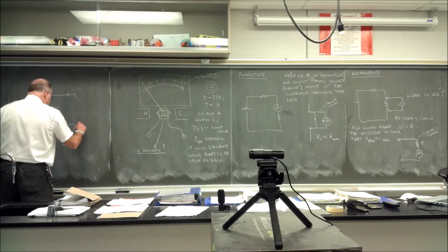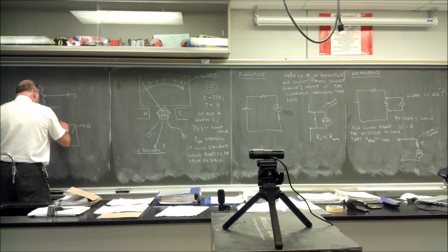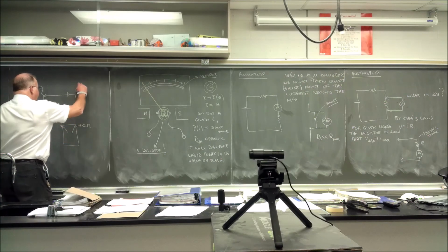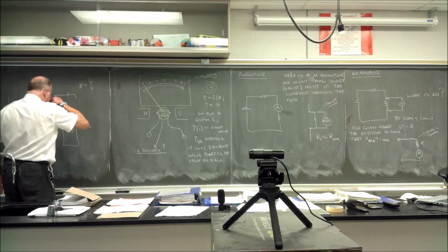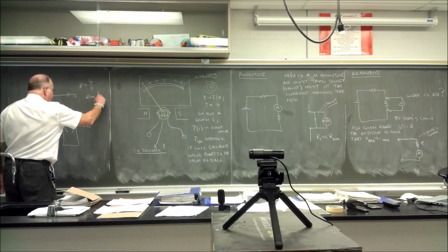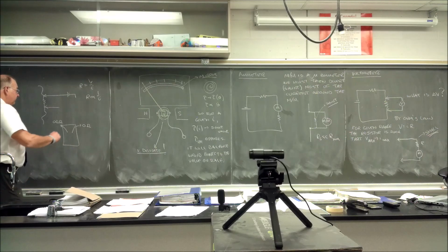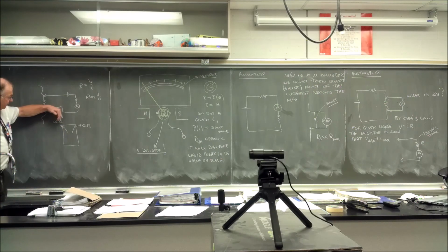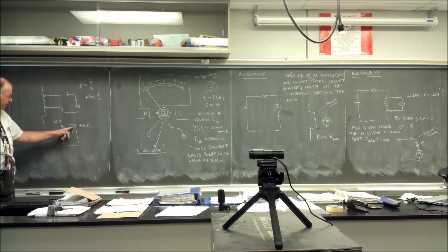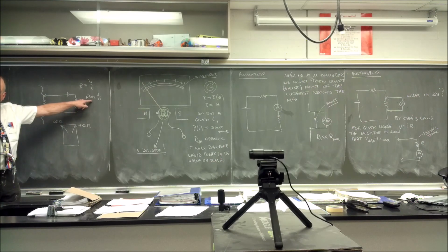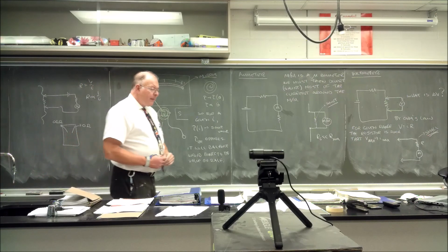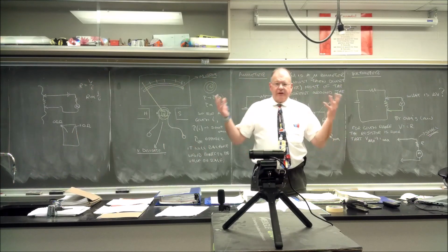So what happens in this case is the scale reverts to an opposite polarity. Over here is 0 ohms, and over here is an infinity value. R is equal to V over I, so the scale is proportional to 1 over the current. There'll be a resistor here for safety and stuff like that, but you get this kind of thing. This thing will go back and you'll see the scale, and it's a 1 over I relationship. We do it in ohms, so you don't know what it is, but it's a function of what the battery voltage is, which is often 1.5 volts or something like that. You don't know that, you just read the scale, because that's what you do.